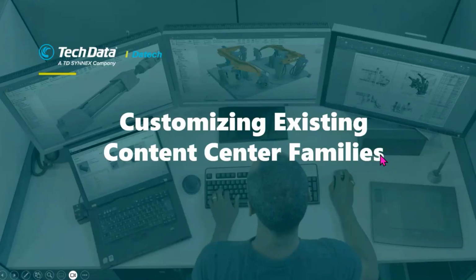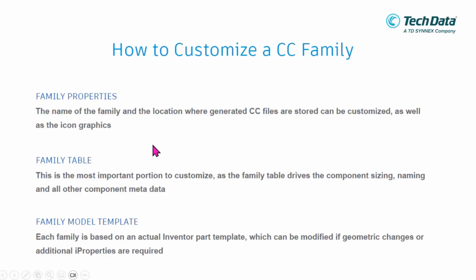So now, customizing existing Content Center families. How to customize a Content Center family? There are three things that we need to know. First, family properties. Family properties is the name of the family files. So let's say you have ISO 7361, maybe with a prefix of your company name.